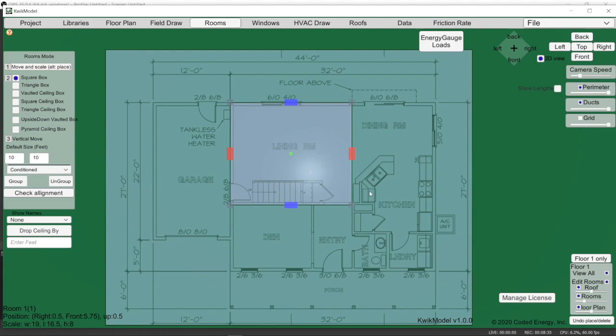The load for both of those spaces will be accounted for because of the way we do the calculations. So it might just shift a little air one way or the other. What you don't want is a 6-inch duct coming down over here and a 10-inch duct coming down over here. You want to even those out as much as possible.